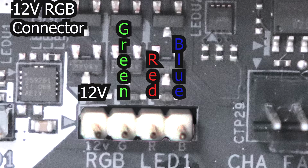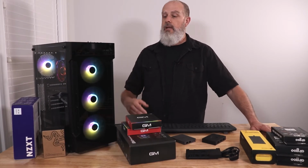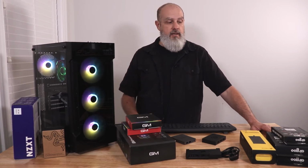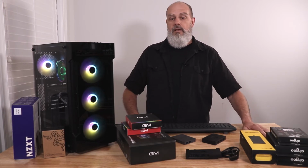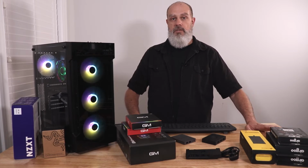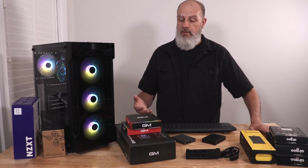I really don't do much with the 12-volt stuff. I have one LED strip that's 12 volt. I was doing a demonstration of that. But really, you can do everything that you need to do with the 5-volt stuff. And that's way more common. You get the cool effects. You can customize and address everything individually. So my opinion really is, unless you've already got some 12-volt stuff and the right connections and everything, if you're going to buy new stuff, just get the 5-volt stuff. Unless you're saving a ton of money by going this way, but even some of the 5-volt stuff is relatively cheap.